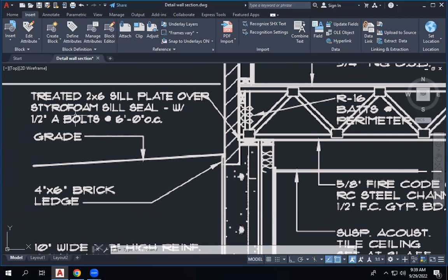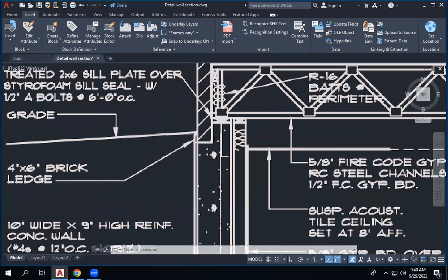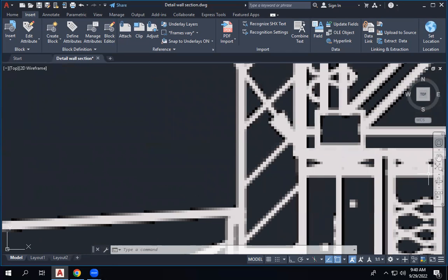Steel. Do we copy paste what we have in the wood? Yeah, you can copy the same thing, but try to keep it different. If you are putting any hatch for this one, I think you have put a cross here. So don't put a cross here, so it will look like the same material then. Just make a rectangle. That's it, and you annotate it on the side, saying that it's a steel plate. The size is here 2x6. So 2 means the height, 6 is the length.